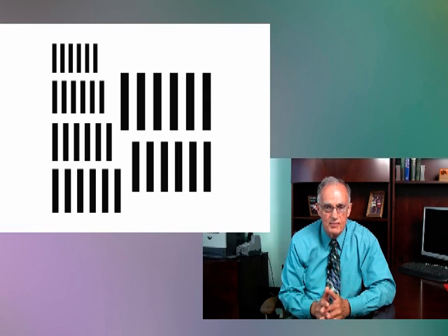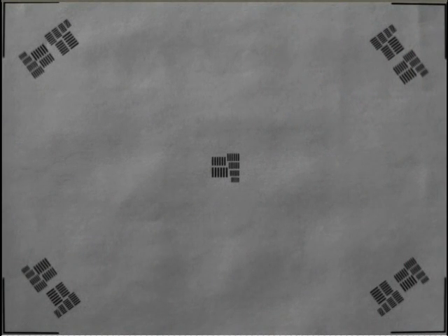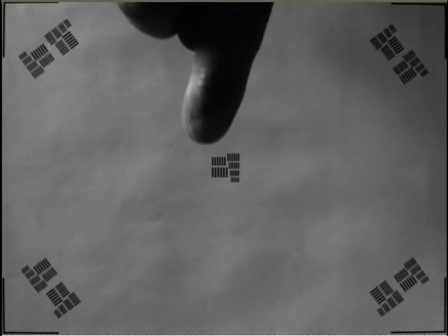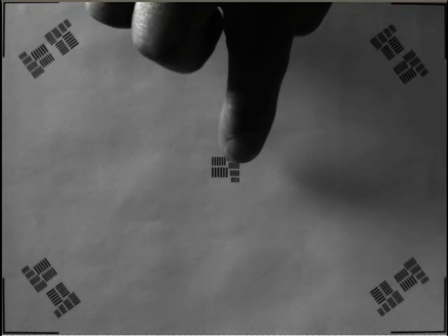Now let's return to the lab to see how we'd use this in practice. Here is the image of the resolution target shown in the monitor. The image sensor resolution, the quality of the lens, and the aperture setting all combine to affect the imaging resolution. You should have documented the components and settings to make sure the system is correctly set up for you to measure the image resolution. Now, you measure the resolution by observing the bar pattern that is resolved in the image. Note the smallest bar pattern.